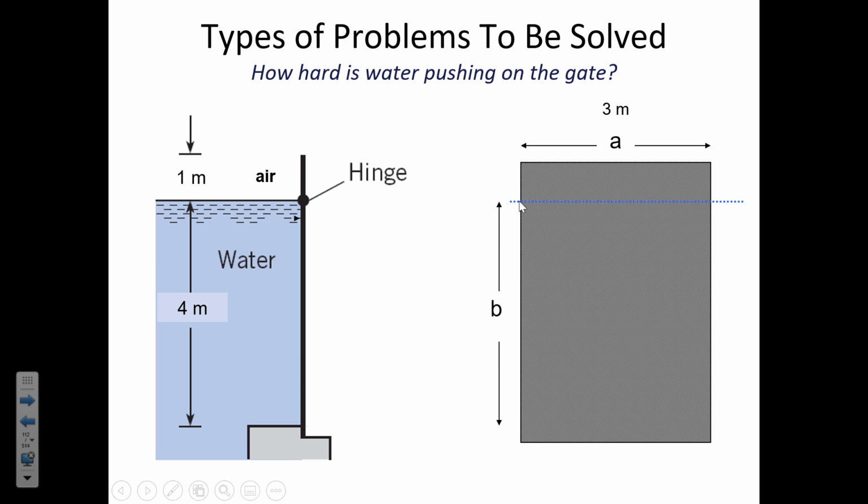B as being the distance from the water line down to the location where the water is in contact with the gate. But it does not include that small overlapping section of the gate that was in contact with the concrete. It's just where the water is pressing on the gate. So that's going to have an influence on the magnitude of the force and also its location. So A is the width, B is the distance from the water line down to where the water is applied.